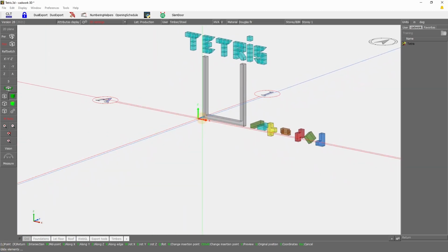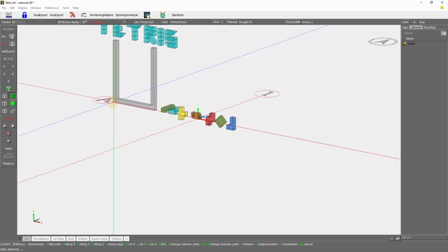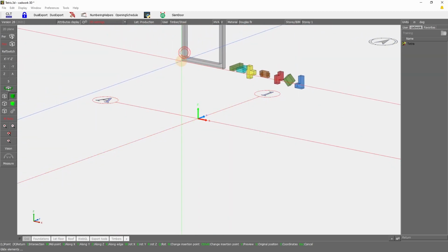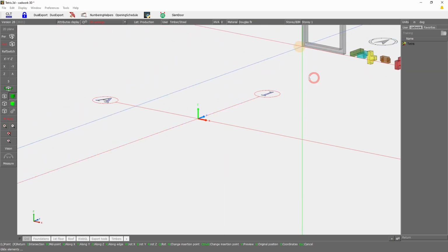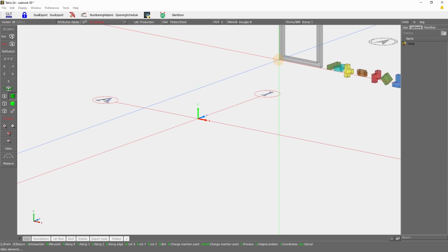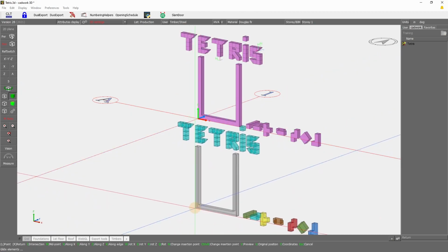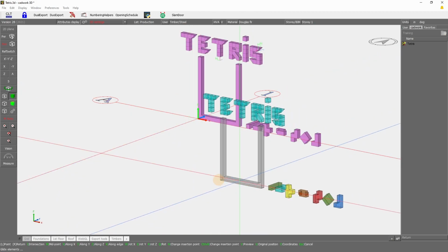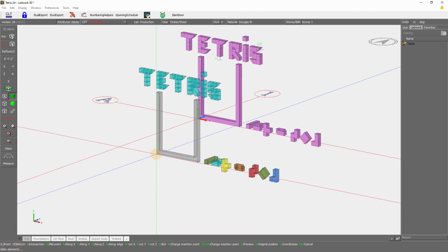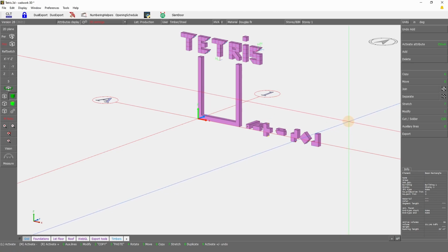The points that are available can be, for example, here the origin, or any points available, so the end of lines, etc., etc. You won't be able to paste it directly in the void since you are in 3D, so there is a third dimension perpendicular to the screen, so you need to select an existing point. When you add a catalog element, you can add them in sequence, so when you're done, simply use the right click to return, and then you will need to do several right clicks to quit the menus totally.